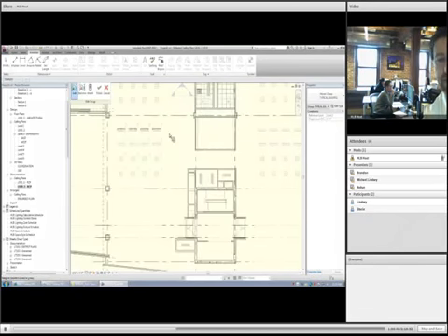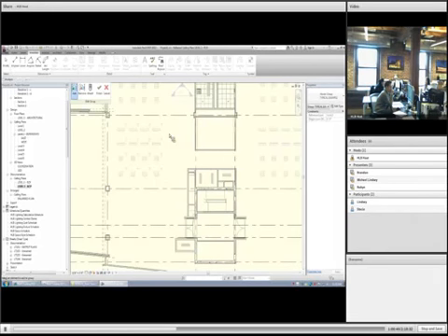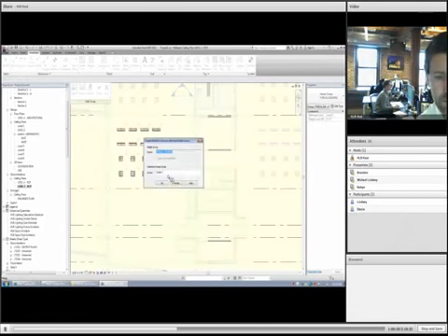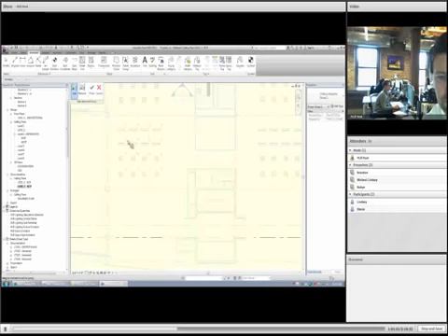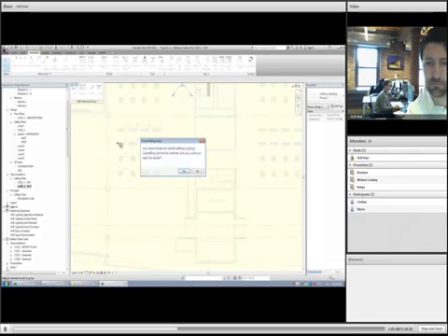It's funny, the annotation is view specific. That's a lot of the reason why you can't add it to a group. I think you actually may just attach instead of that. Is that doing it? When you do that, you click attach, you then give it a name. Call it whatever our array is, plus tags, and then you can select.